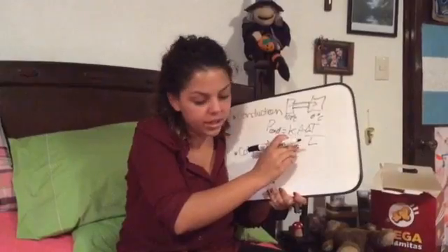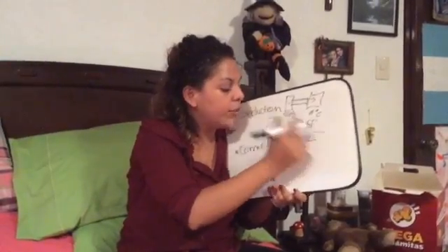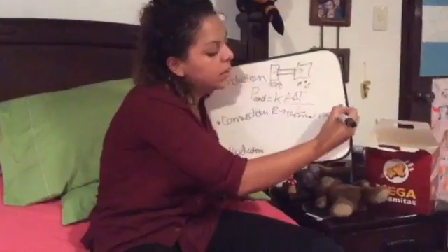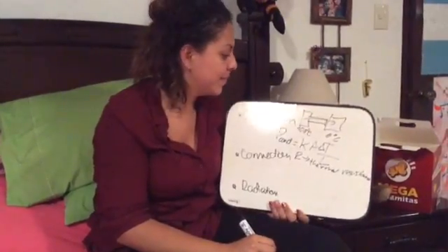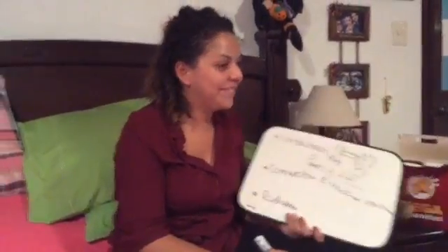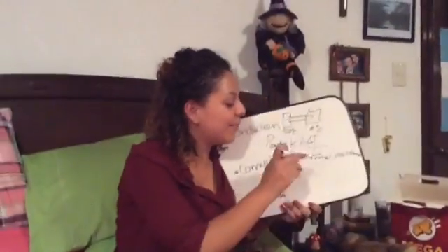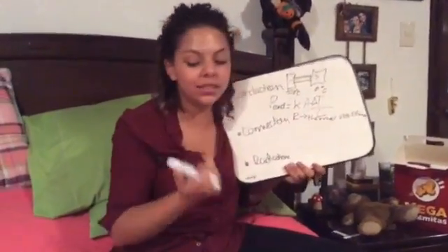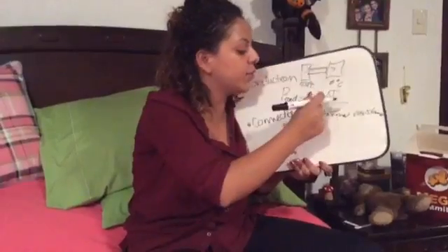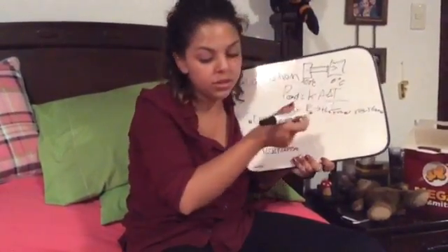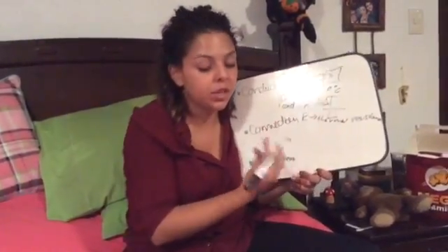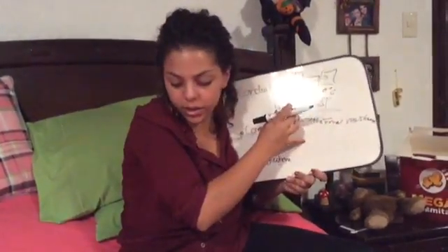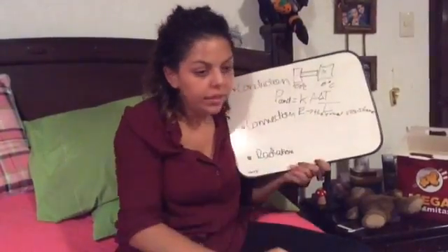We can also use L over K as a constant R. This value of R is also known as thermal resistance, and it is represented as L over K. So we can have this formula as the area times the difference in temperature divided by R. And this is specific to each object because it depends on the thermal conductivity and the length of the object.